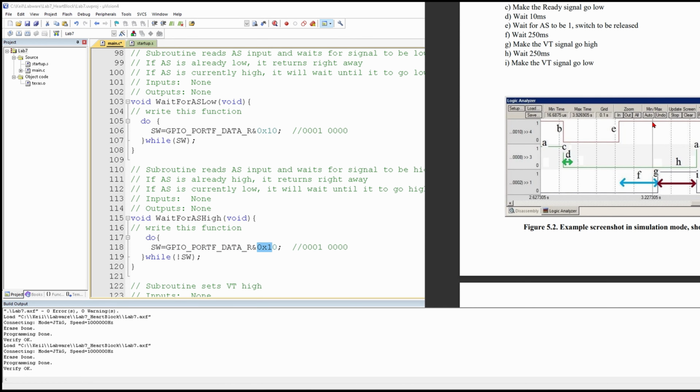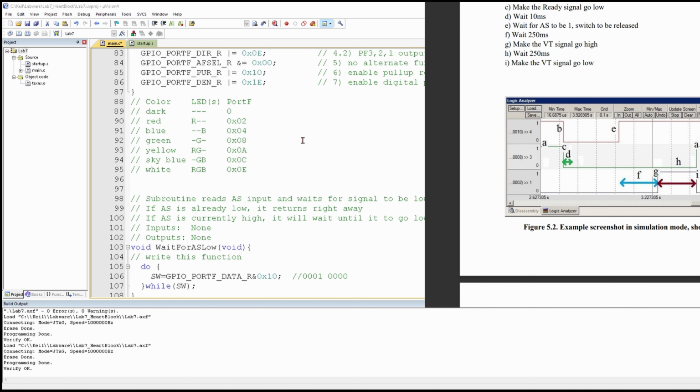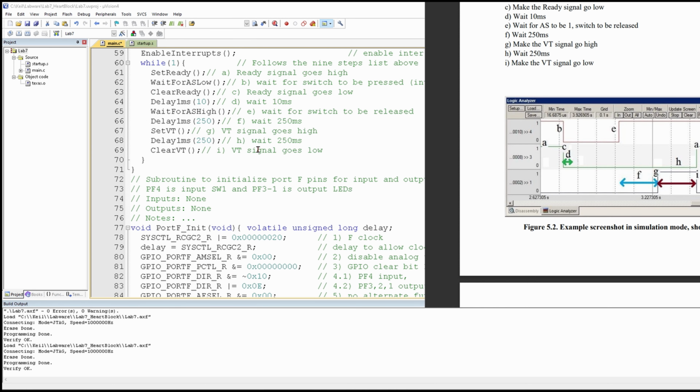It's going up here. It's similar to our A. There's no inverse because our A is solid right here. It only drops with our C. And we covered the C earlier. It's a ready signal go low. When it goes low, it's going to be the inverted part. We're going to delay for 1 millisecond again, times 250. So we're waiting for 250 milliseconds.